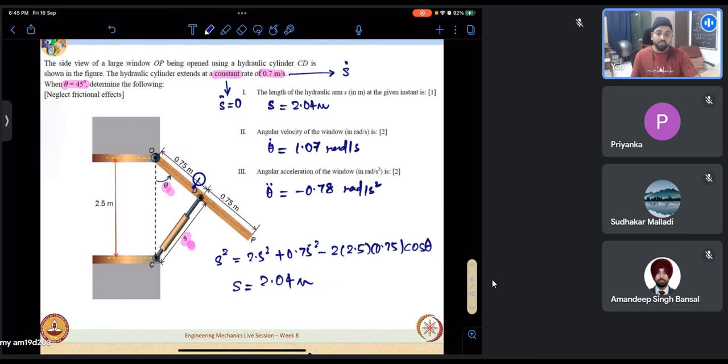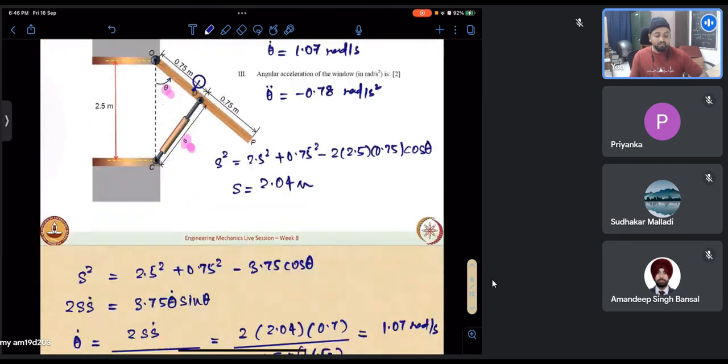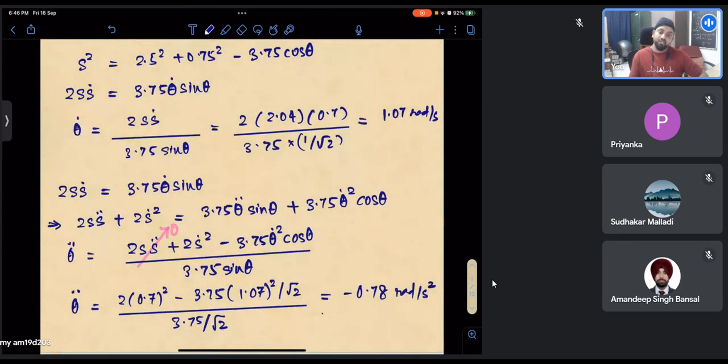What is the linear velocity of any point? Anything that is in contact with it will also have that linear velocity. That is the constraint here. Based on its velocity, which we know, and the linear velocity of the point on which it is sitting, we can do a vector sum and get the total absolute motion that it is having. That is the essence with which we proceed and decompose the components.